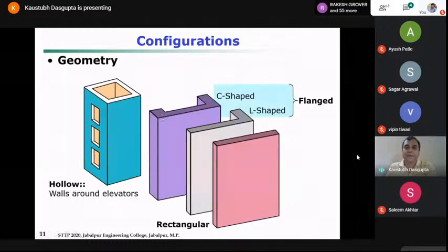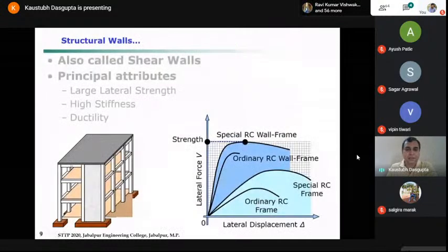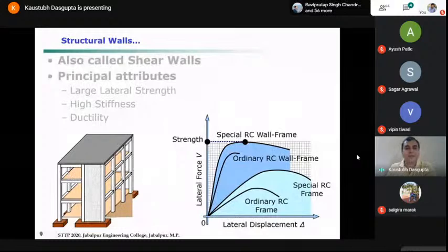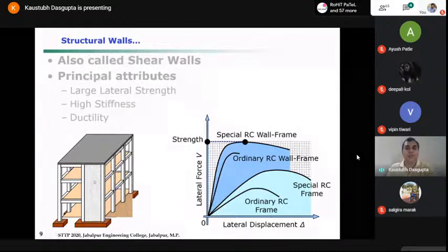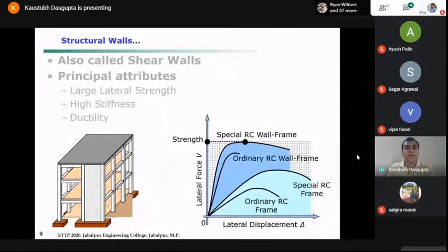Then you have different shapes of walls depending on the requirement of lateral load resistance. So in our previous figure here, the wall was only along the width. Along the length of the building frame, there is no wall. So if you have large shaking along the length of the building, this wall, okay, will not be effective. Why? Because in the longer direction of the building, you have the dimension of the wall as its thickness. Okay?